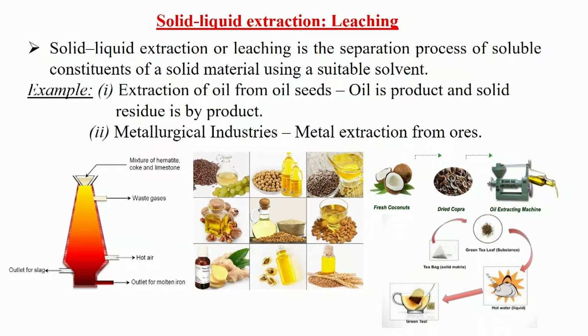Before that, we will be discussing the leaching process and how it is different from other separation processes. In the previous chapter, we learned about the liquid extraction process, or LLX. There the feed was in the liquid phase, where a carrier solvent and the target component to be extracted were there, and in that feed the extracting solvent was added.